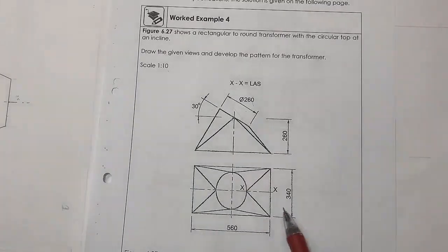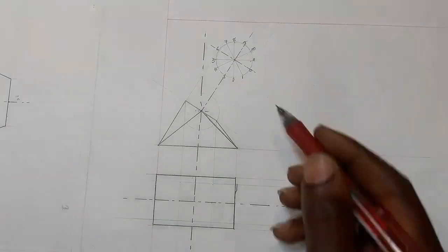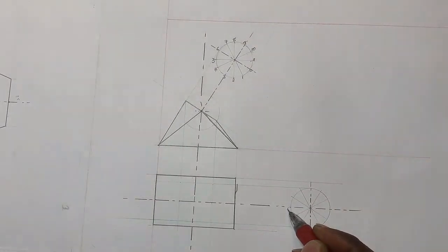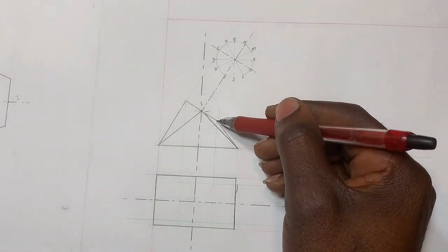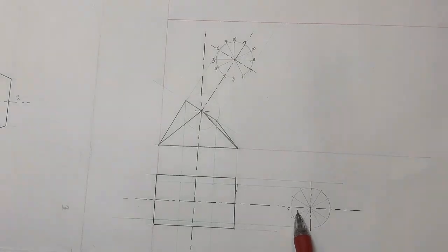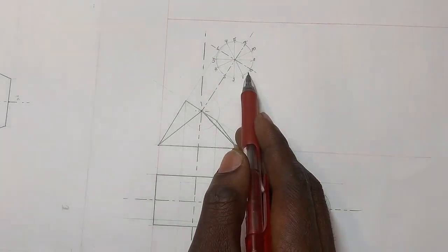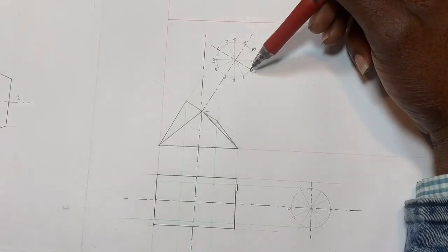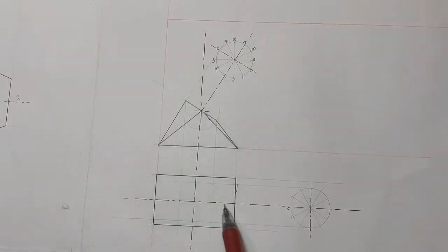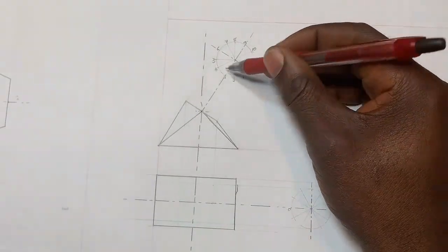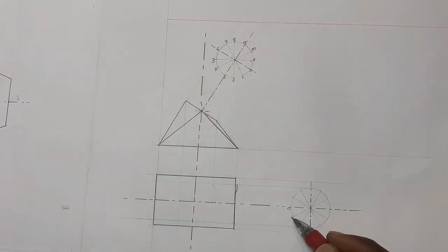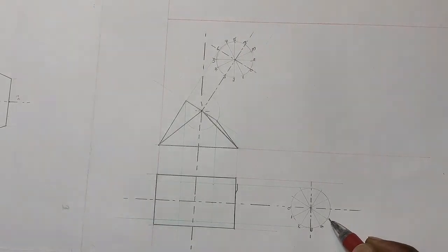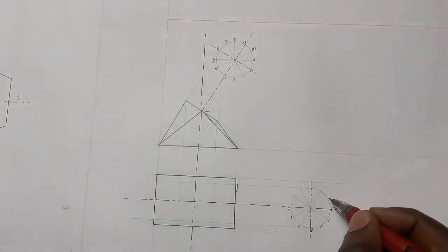And luckily enough, we're even given the cutting plane there. So this 0, I'll then put my 0 here, so that this 0 that goes to touch there goes vertically down. It's going to intersect with this one, and my 0 is along the center line, isn't it? Which is this one. The same applies to this one, it must be within the center. You understand? So this is it. This side I was going clockwise, which means this side I must go anticlockwise. So 0, 1, 2, 3, 4, 5, 6, 7, 8, 9, 10.